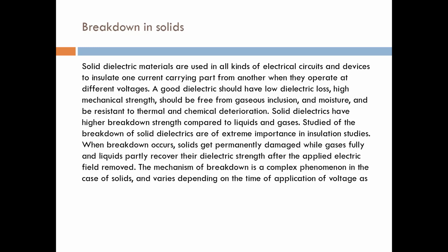These are low dielectric loss, high mechanical strength, freedom from gas inclusions and moisture, and resistance to thermal and chemical deterioration. I have told you that solid dielectrics have a higher breakdown strength compared to liquids and gases, so the study of breakdown of solid dielectrics is very important for insulation.